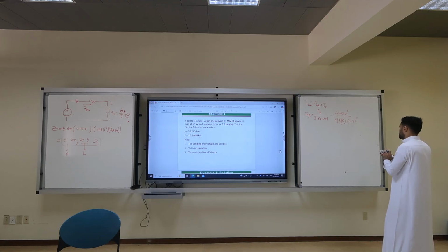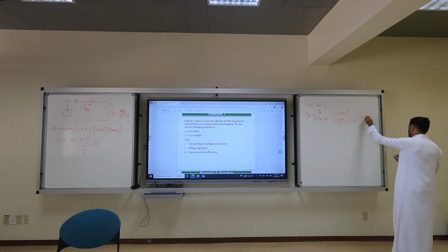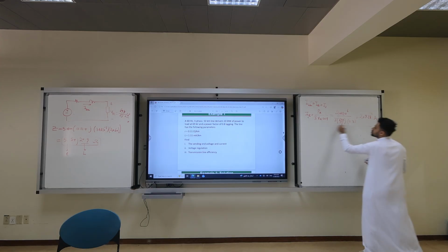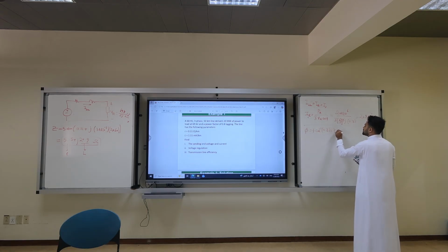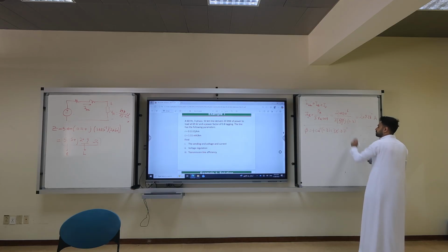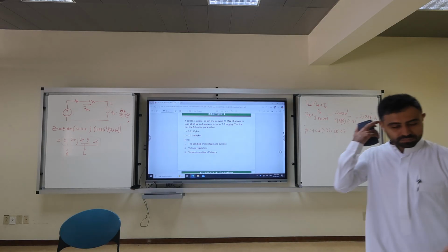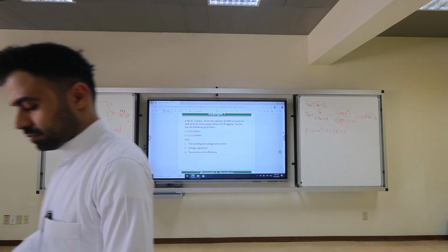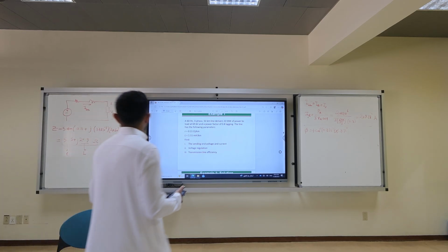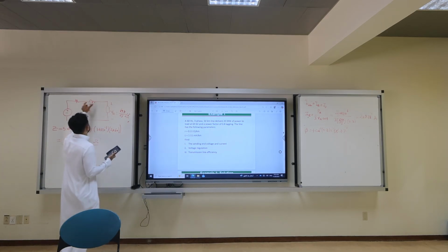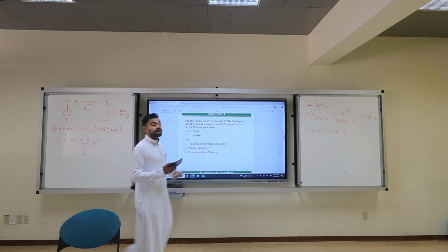It's 209.184. Yeah, you're right. So what is theta? Because it's lagging, cosine inverse of 0.8, which is 36.87. Z is R plus jX.